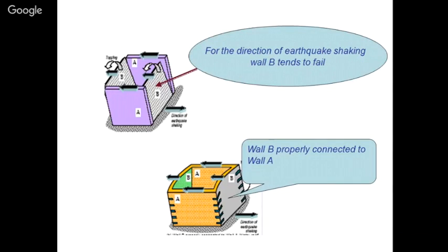That is why we need to maintain the main wall to cross wall connection, and the wall to wall connection with the slab. Unless that anchoring, that connection, is there, there is definitely going to be a future earthquake which is going to collapse your building. So if that is your wish and your method, how are you going to maintain that connectivity with your walls, wall to cross wall and wall to slab?